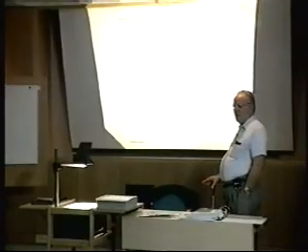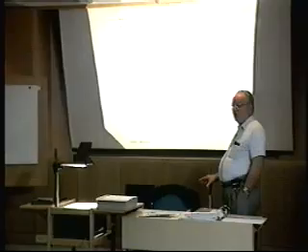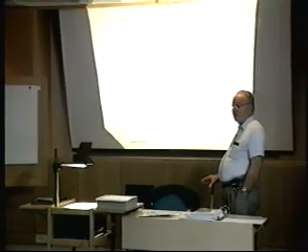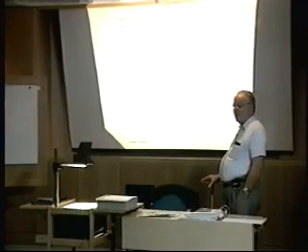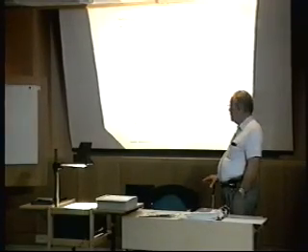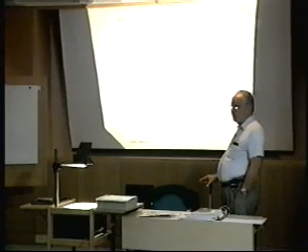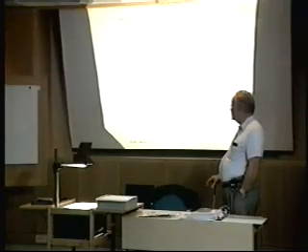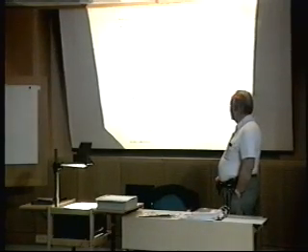and it was only through the understanding of rate time analysis and performance data that existed in that region that we were able to kind of discover layered no crossflow reservoir behavior and its implications. And again, I hope to go over that with you in detail. There's a lot of potential for increased production and reserves if you understand what's going on. And the first day we're going to cover basically rate time decline. And again, I'm going to try and throw in, while we're going through it, its bearing on layered no crossflow reservoir behavior.